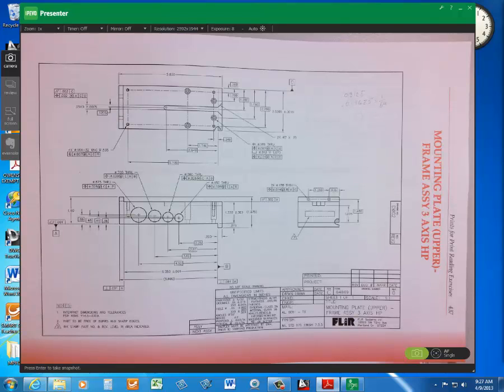These kinds of gauges that we check for sizes out in production are called go, no-go gauges. They're just little rods, and on one end is one size and the other end is another size based on our range of tolerance. So we would have a specially made go, no-go gauge that's 0.312 to 0.316.